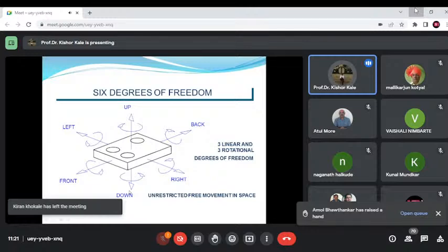Now, what are the different steps for the CMM tactile program? Tactile means it touches the parts. So probe and stylus qualification, how to decide which probe and stylus to be used, then how to align the parts, this is important. Once then we do the inspection process, data fitting and verification, then measurement report design, measurement program test, measurement program revision and improvement. These are the steps in the CMM.